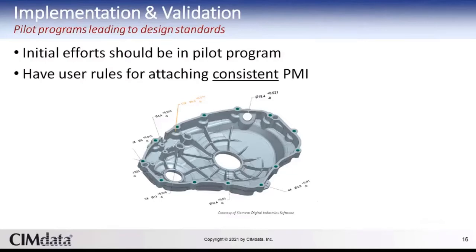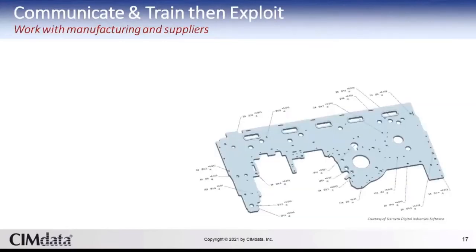We recommend that your initial efforts be done as part of a pilot program. You really do want to avoid a big bang change in your workflow. Probably the most important aspect to the use of PMI with MBD is consistency. The PMI is data expected to be read by downstream apps. It needs to be in a stable form and content to be consumed by those apps. Simply telling your designers to create PMI this way does not guarantee consistency. We recommend you use whatever tools are provided in your CAD solution to assist. And if you have the capability to do a software-driven check, do so, since it's the validation process that will help you catch errors.